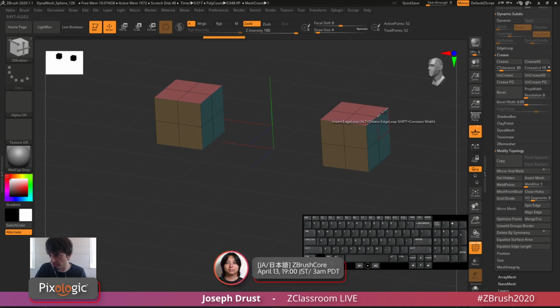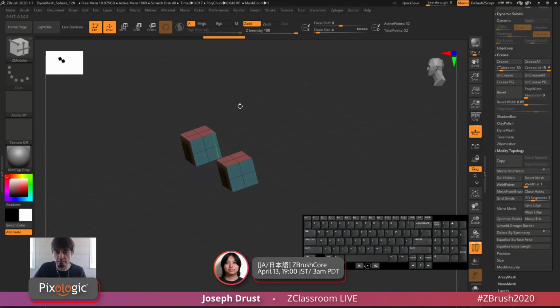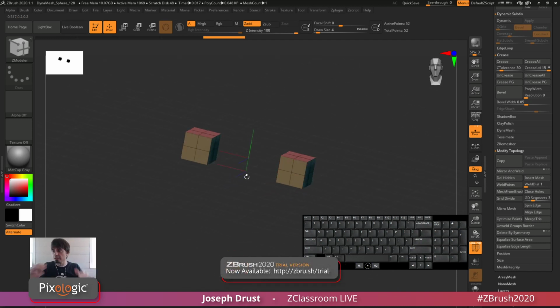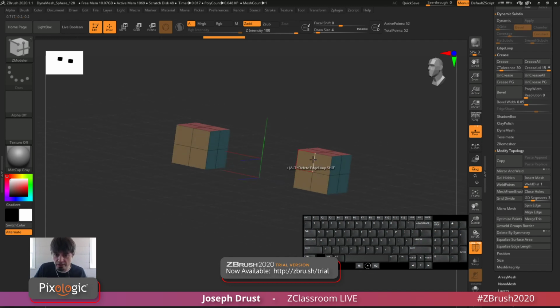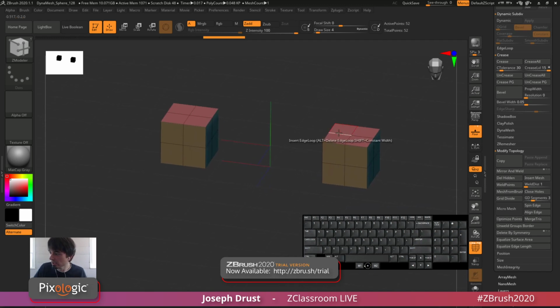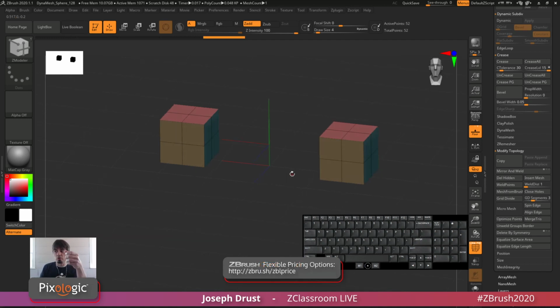And we had a question about how you can make a hull of a Viking ship. So basically I'd model the back of your ship, and then for the front bow part, what we can do is use the Bridge to Holes option here, and it'll make a curve from one side to the other, and it gives a pretty nice result. You can change the splines, the variables or the modifiers on it, and it'll give you this nice curved shape. You can do this with a lot of things. If you're making pipes, you can generate one pipe here and another pipe here and then bridge those two holes, and it'll make that nice curved surface.